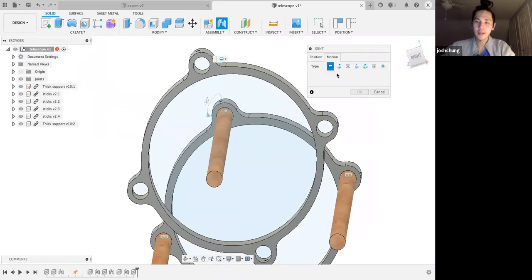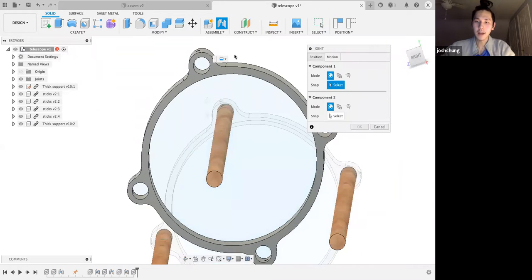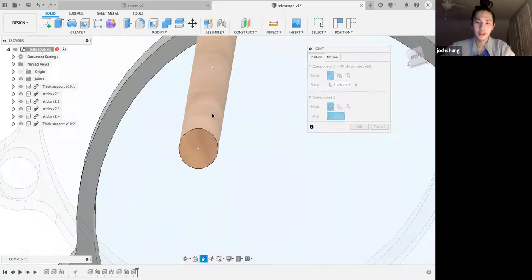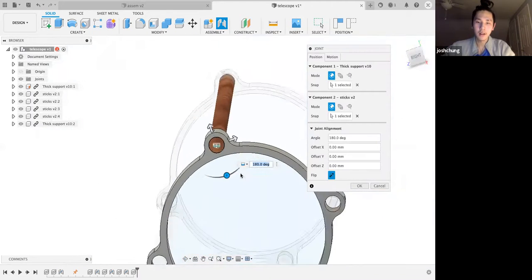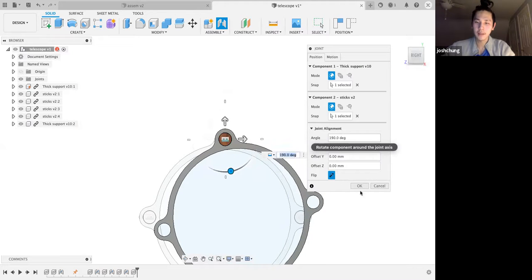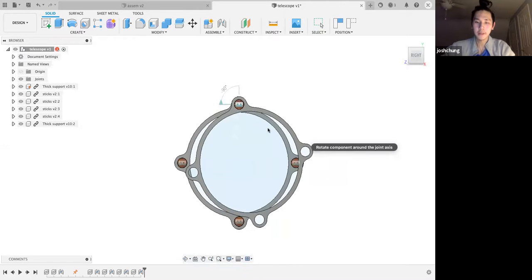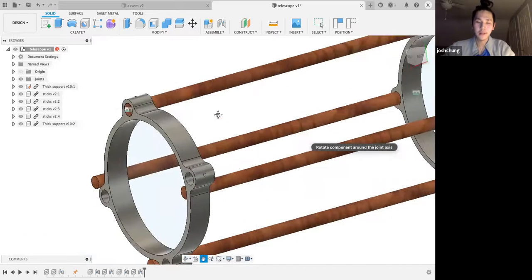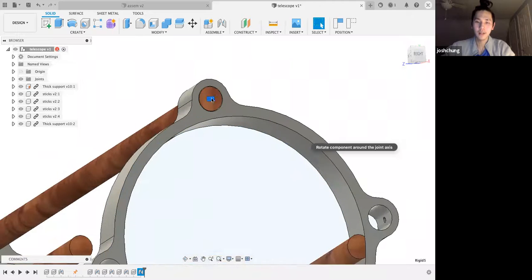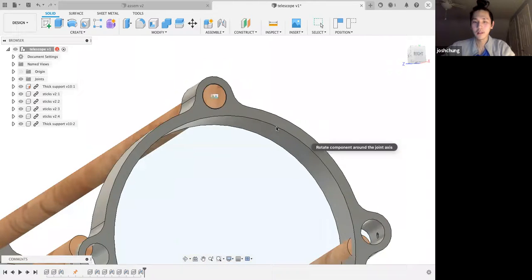And in this case, it would be fine to apply a rigid joint because the angles are pretty similar. But if we potentially do it wrong and it's tilted off a slight bit, we get something like this. The final support is tilted a little bit, but now since it's rigid, the constraint, it can't really rotate anymore.